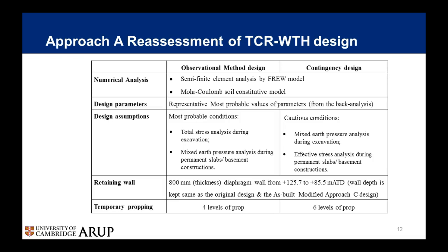So basically, they are using the same semi-finite element analysis program and using the Mohr-Coulomb soil model. And in order to keep things more comparable, I tried not to change too much about the design, so it's only the wall thickness that has been changed from 1 meter thick to 800 millimeter thick for the reassessment design.